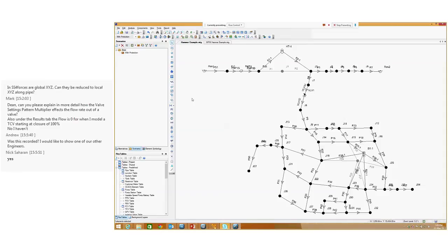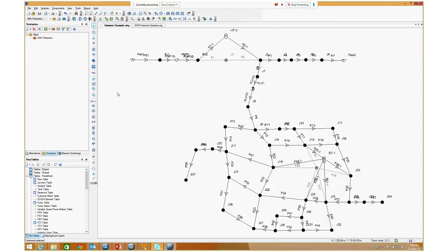Yeah. So, Mark, just quickly on your question there, the steady state that I'm referring to, what you may need to do is have flow going around that in an artificial manner, and I'll explain that in a bit more detail maybe offline or something. But what you'll need to do is have your steady state with flow through it, and then your transient with the valve closed, so that they're slightly different.